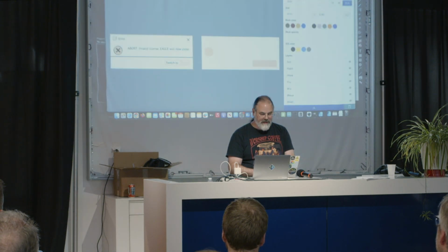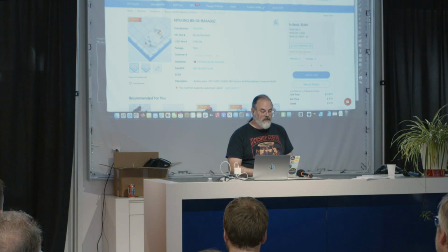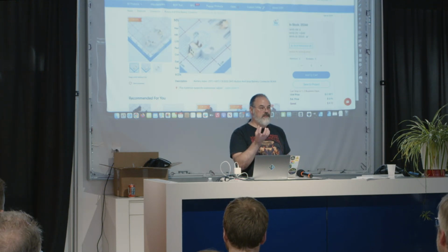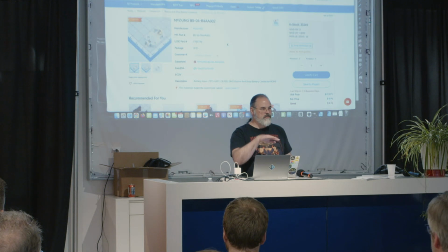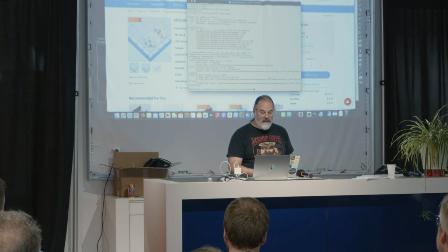There we go. Go over here, and I found a random part on LCSC, something that I wanted. It looked pretty decent, nice contacts, stuff like that, a nice kind of case to hold it in there. So you can do metal clips and stuff like that, but this seemed like pretty nice. And I just copy this ID, basically, go down here and run this easyeda2kicad, paste in the ID here, and it pulls it into a KiCad library for me automatically.